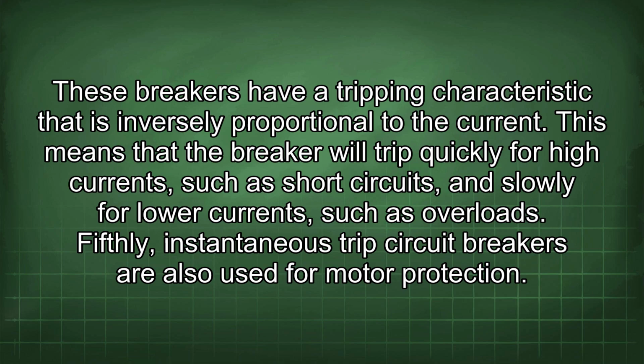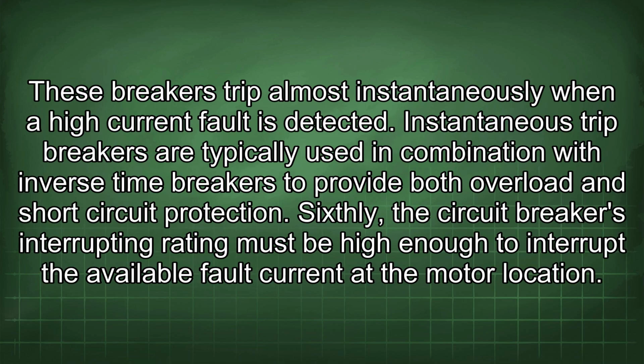such as overloads. Fifthly, instantaneous trip circuit breakers are also used for motor protection. These breakers trip almost instantaneously when a high current fault is detected. Instantaneous trip breakers are typically used in combination with inverse time breakers to provide both overload and short circuit protection.